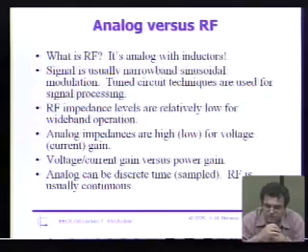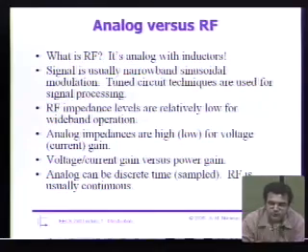In RF circuits, usually we're dealing with narrowband signals. Somebody modulates a signal, and the modulation is much less than the carrier frequency. So you might be transmitting at a gigahertz and have 100 kilohertz or megahertz of modulation. For all practical purposes, your signals are narrowband. That's really nice because you can use tuned circuit techniques. You can put in inductors and resonate out capacitances. That lets you push your transistors to higher frequencies than you otherwise could. Almost all the circuit techniques are in some way sinusoidal, so frequency response is very important when you're dealing with RF circuits.